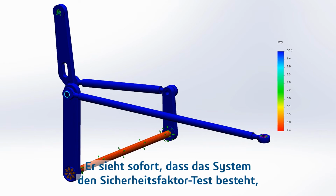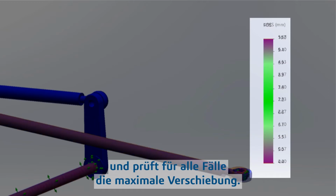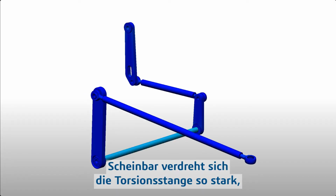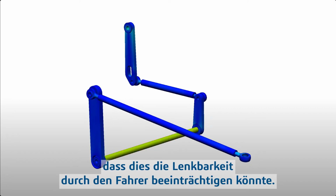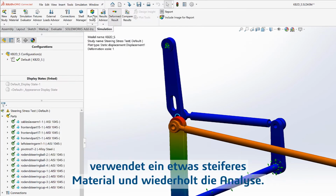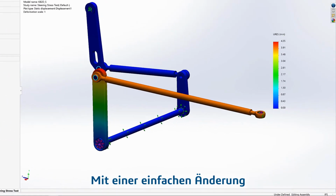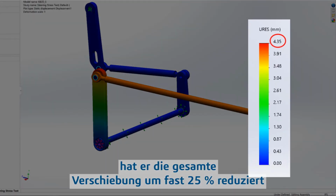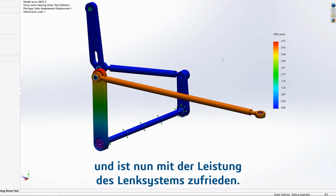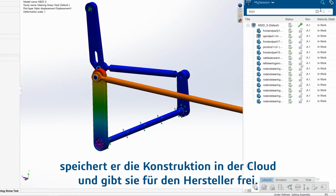He can quickly see that the system passes the factor of safety test, and then checks the maximum displacement just in case. It appears the torsion rod is twisting so much, it could affect the rider's ability to control steering. He changes the material of the torsion rod to something a little stiffer and reruns the analysis. With one simple change, he's reduced the total displacement by nearly 25% and now feels comfortable with the steering system's performance. To complete the task, he saves to the cloud so the design can be shared with the manufacturer.